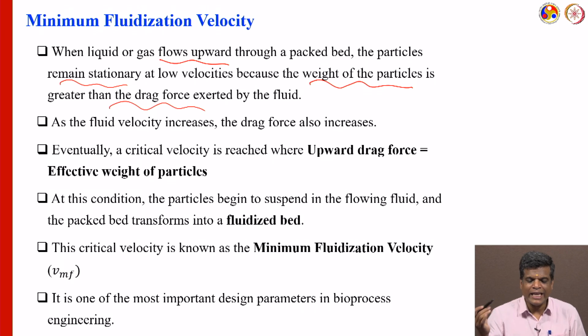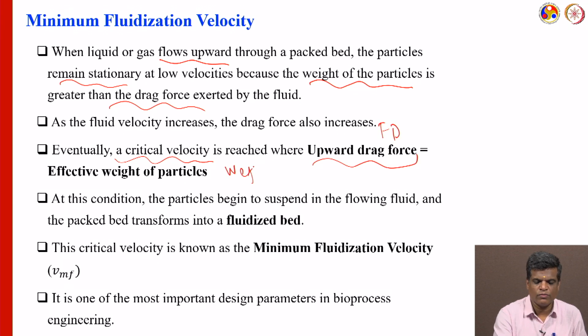As the fluid velocity increases, the drag force also increases. Then we reach what we call the critical velocity, where the upward drag force, which we write as Fd, is equal to W effective. Both are equal.